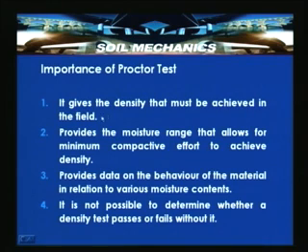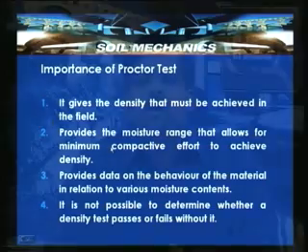That is possible, depending upon the test, either with standard compaction or with modified Proctor compaction. You can determine the density that must be achieved in the field, and it provides the moisture range that allows for the minimum compactive effort to achieve the density. So it also tells us in what range the soil should be maintained so that the maximum density can be achieved. Otherwise, for a given soil we will not have this information, and we will face difficulties in compacting the soil.